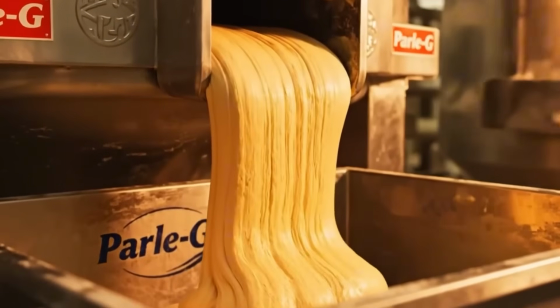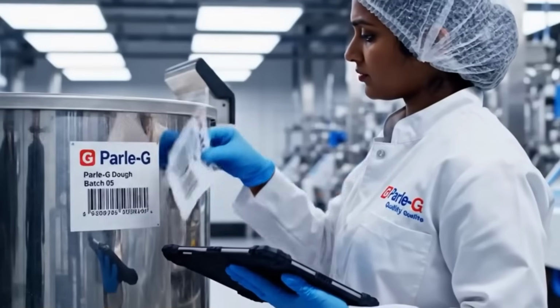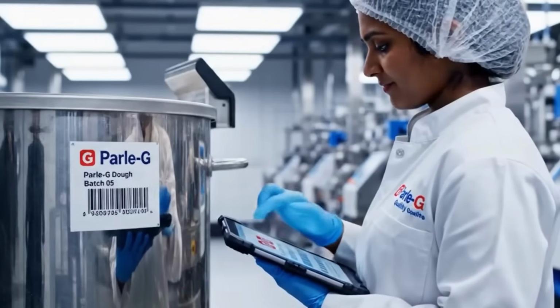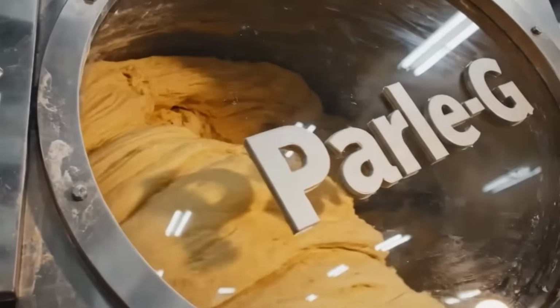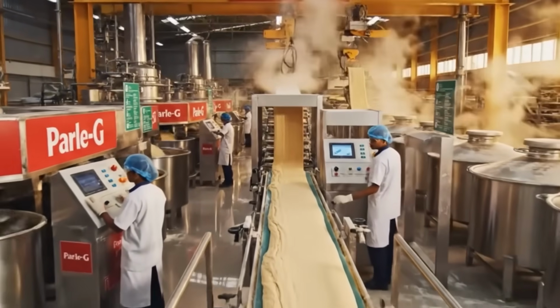For molded biscuits, a rotary molder can be used. Dough is pressed into engraved cavities on a roller and then released onto a conveyor. This method creates surface patterns and can handle softer dough. Release depends on dough fat level and temperature. If dough is too warm, it smears in cavities. If too cold, it cracks and does not fill details.